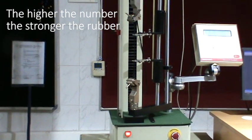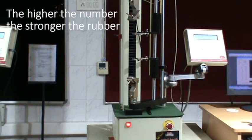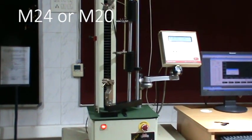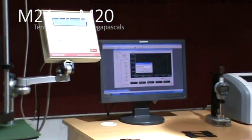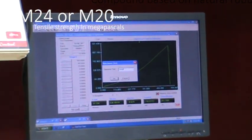The tensile strength of the rubber is closely related to the rubber's resistance to cutting and gouging by sharp objects. Belting with rubber covers of higher tensile strength are often quoted as being M24 or M20, whereby M signifies it is a compound based on natural rubber, and 24 or 20 denotes the tensile strength of the rubber in megapascals.